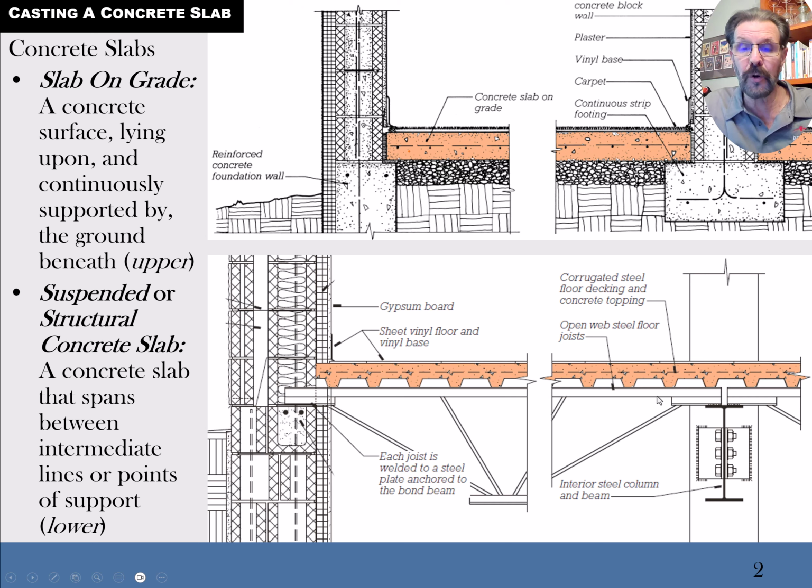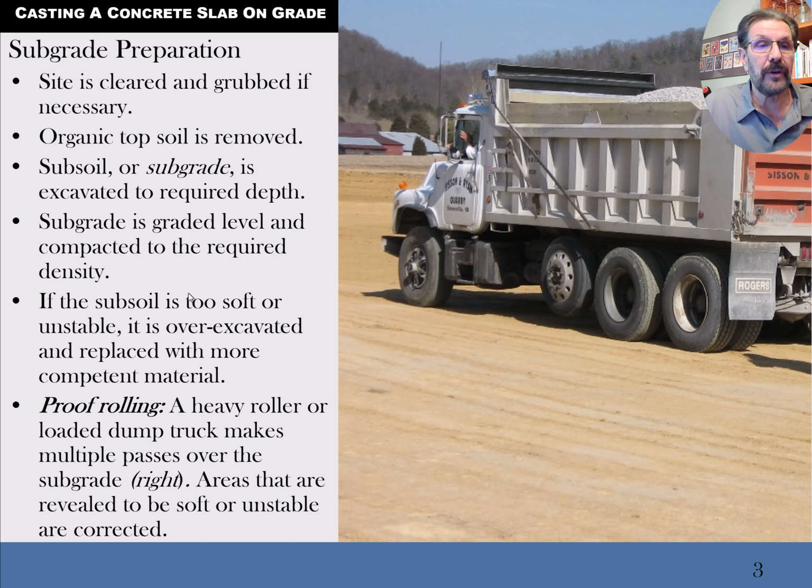And then you've got corrugated steel decking on top, and that's typically, most structural steel buildings are done that way. And then you've got a corrugated steel deck with concrete, maybe 3 inches worth of it on there or more. And so that's a suspended slab, or an example of a suspended slab. But any slab that's up in the midair where it's a load-bearing item, but it's not on the ground, it's a suspended slab.